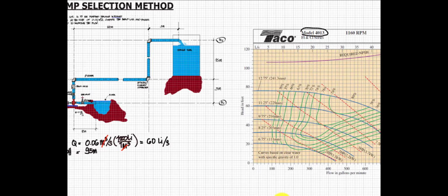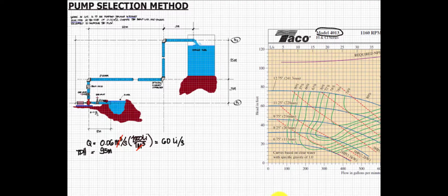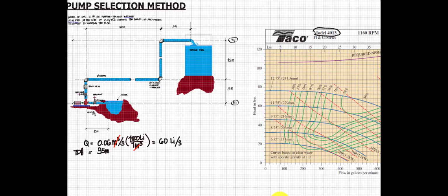Refer to another pump characteristic curve which will suffice your design. So maybe if you're going to install this one, it will provide you a low flow rate and low pressure discharge at the end of this pressure storage tank. Maybe it cannot reach this type of tank. It will not reach this head. So this is a long piping, 100 meters by 5 meters, with a given elevation of around 20 meters from the zero elevation.